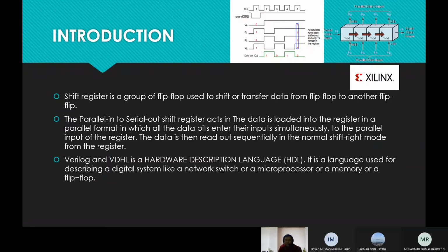Shift register is a group of flip-flops. A shift register basically consists of several single-bit D-type data latches, one for each data bit, either a logic 0 or a 1, connected together in a serial type arrangement so that the output from one data latch becomes the input of the next latch and so on.